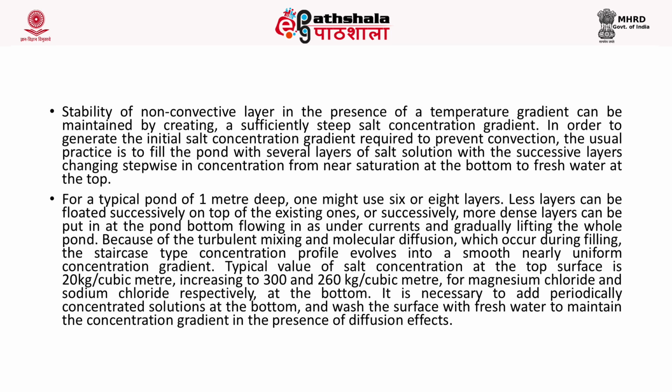Less dense layers can be floated successively on top of existing ones, or successively more dense layers can be put in at the bottom, the pond bottom, flowing in as undercurrents and gradually lifting the whole pond. Because of the turbulent mixing and molecular diffusion which occur during filling, the staircase type concentration profile evolves into a smooth, nearly uniform concentration gradient.